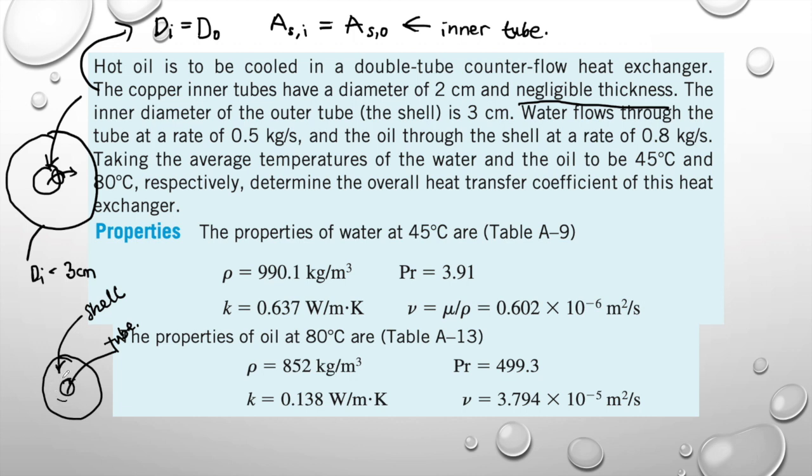We have an annulus here. Previously I mentioned that I will explain this annulus more in the heat exchanger topic, including the annulus calculation. If you get turbulent flow, it will use the same equation. But if you get developing laminar flow, then there will be something different. You have to refer to the tables to get the value of the Nusselt number. Later on you will understand this.